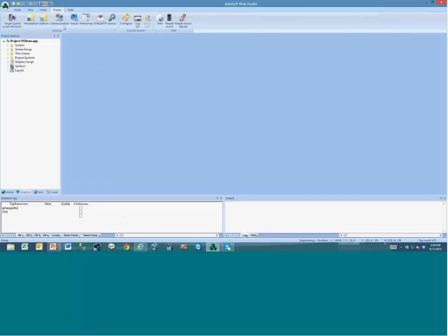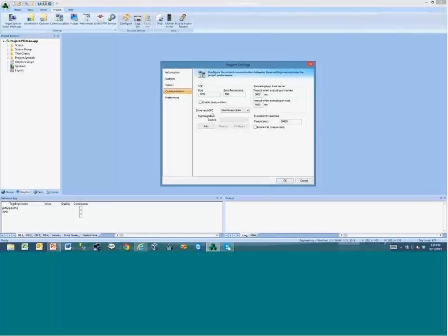In the project communication, there is a very simple but very important setting where, for driver and OPC, you can define send last state or send every state. It affects the writing commands to the devices only, and does not affect the reading at all. If you select send last state, on each cycle of the driver, it sends only the most current value of the tag that needs to be written to the PLC.